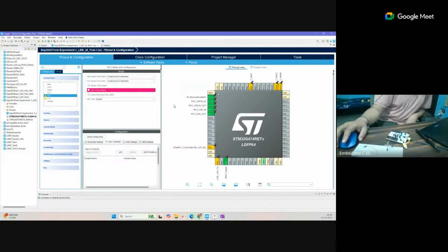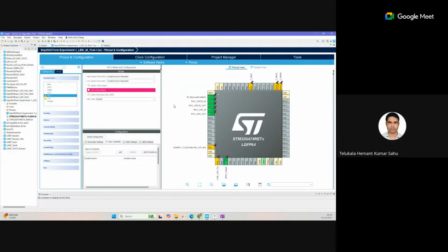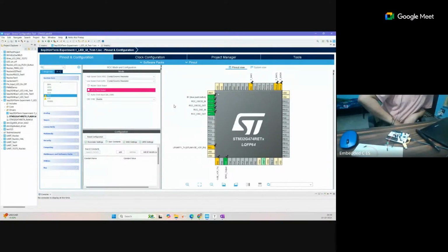Control S. Sir, for the functioning of this STM32, do we have to select any supply voltage, ground, anything? No. By default, 5 volts is coming to this board, and all the power is managed by it. We do not need to enable or disable any voltage here.